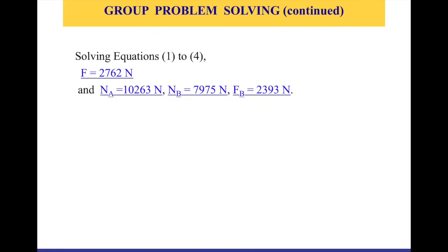And that concludes our video, in which we talked about the steps to solve a system in static equilibrium, and in which we included and accounted for friction, and we solved an example in doing so. Keep in mind that we are doing the same thing since the beginning of the semester when we are analyzing static systems: we want to add the forces on a free body diagram and then construct the equations of equilibrium and then solve them.